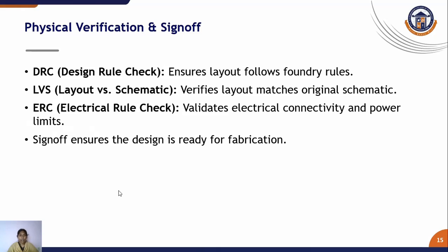After that we follow the electrical rule check. Here we validate electrical connectivity and power limits. So sign off ensures the design is ready for fabrication. Once we verify everything, the sign off ensures the design is ready for fabrication.